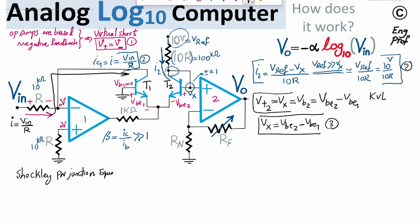The voltage of the junction, in this case base emitter, is equal to eta, the ideality factor of the transistor, times the thermal voltage Vt times the natural logarithm of the collector current of the transistor divided by the saturation current of the transistor.